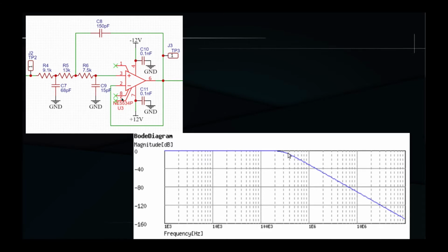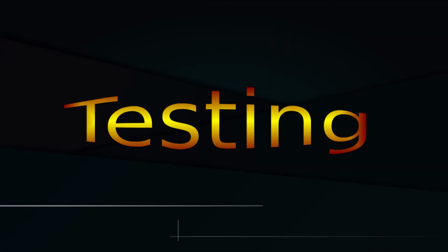When the signal coming from the volume variable oscillator changes in this interval, we can catch it in this region of the filter, and then we can take the amplitude of the output signal to drive the voltage controller attenuator. This should work much better than the circuit used in the previous design, the old Theremin V.1 from last year. Let's now take a look at how this filter behaves in a lab test.